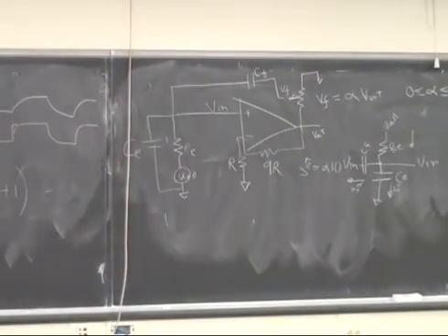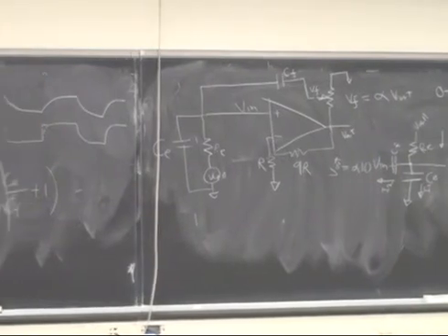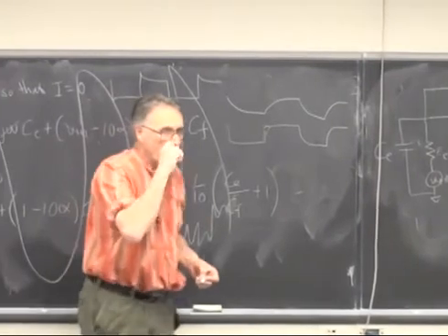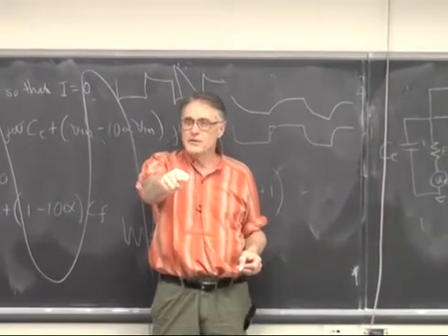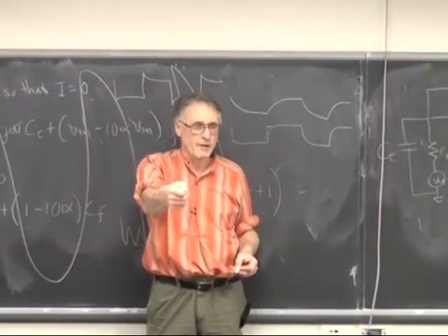So you can't actually get to perfect squareness, because if you do, something else will blow up. The system will start to oscillate too soon. So there are noise limitations, but it allows you to choose the trade-off between noise and bandwidth that is best for your particular application.